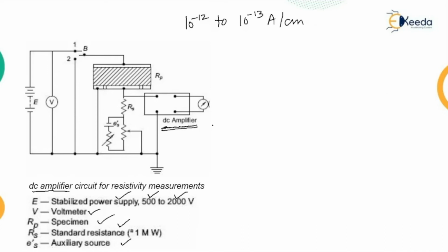A separate potentiometer circuit is used for obtaining a signal E equal and opposite to the voltage drop across the standard resistance RS. At balance, the voltage drop across RS is effectively made 0. Any AC voltage appearing across the standard resistance RS is amplified only by the net gain of the amplifier, which is small.